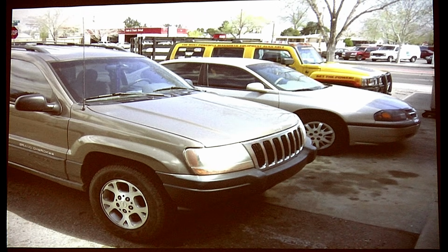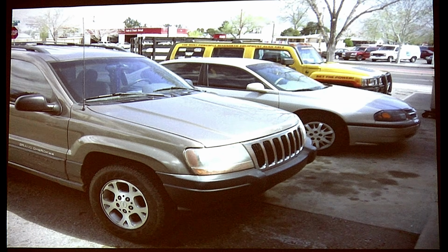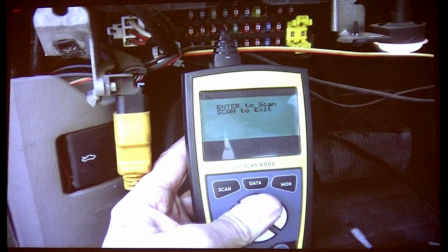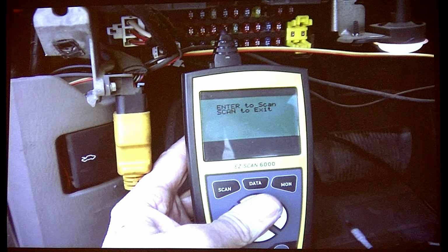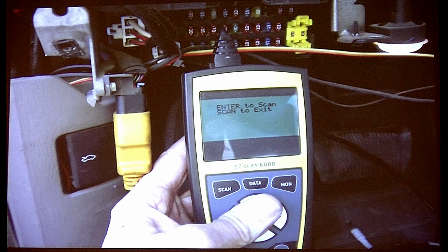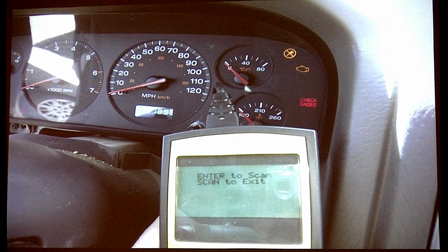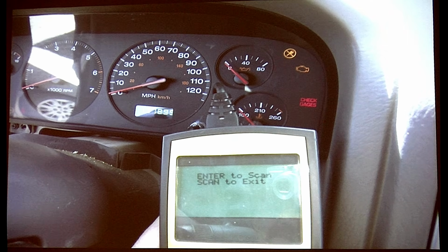A while ago when I first wrote this course, this was in '08 and I've revised it recently, but this is a car that I was called out to look at. The individual has no dash, his dash is out, and I'm using his scan tool. So this is the shop scan tool where I'm at. Do you see how all the dash is dead? We plug this scan tool into the bus system, and now the whole bus is down. Now, he didn't realize that the scan tool is taking the bus down.